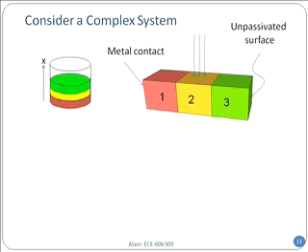In the middle yellow region, light is shining, right? And this is an unpassivated surface, which is simply giving you a clue that you should consider surface recombination. That might become important. So every statement here is trying to give you a clue of how to make the approximation.